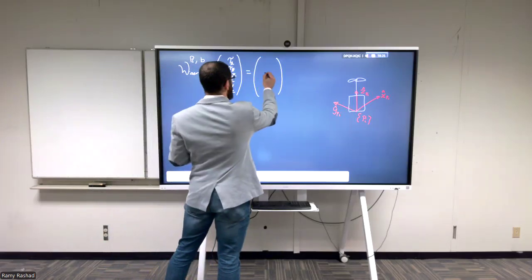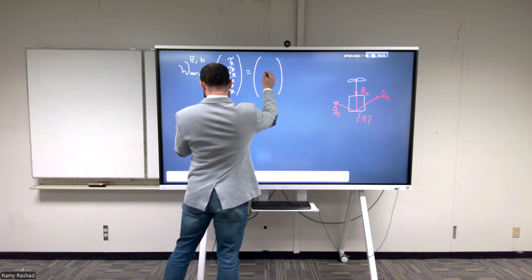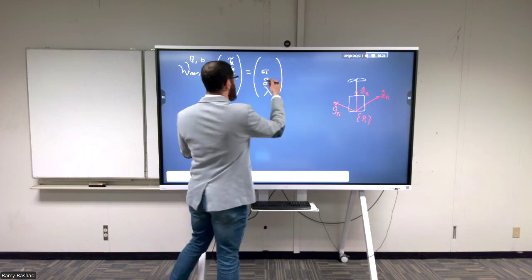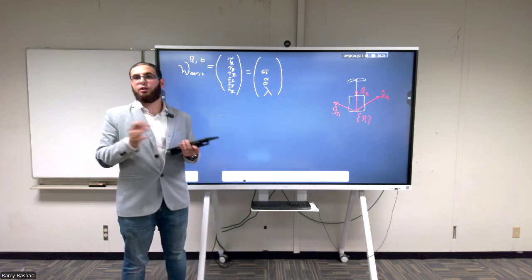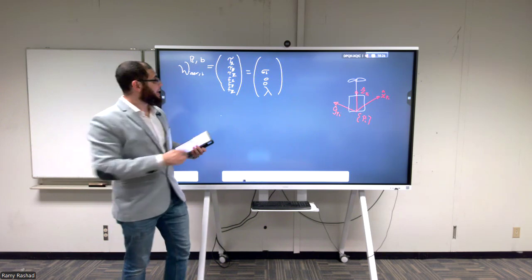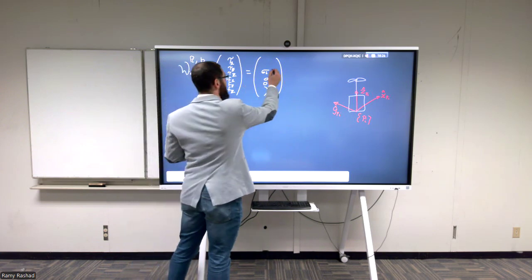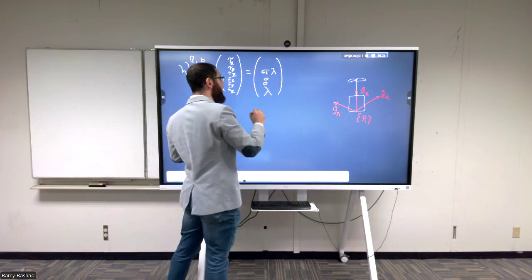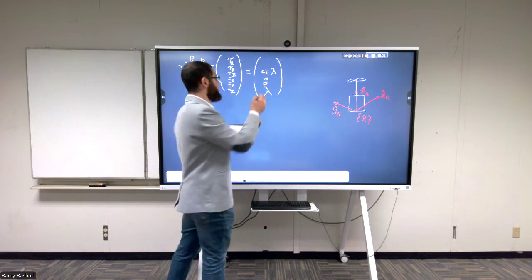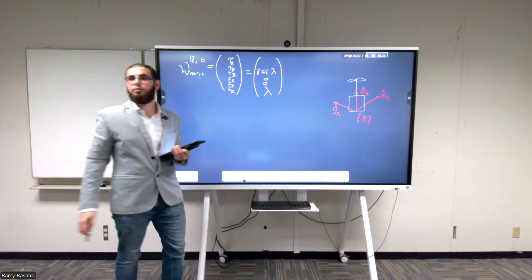So we're going to have here some sort of sigma I multiplied by a torque, but there's a modeling assumption that's very valid, and you can show it in practice, that the drag torque that's produced is usually a constant, or a fraction that we're going to be calling gamma, multiplied by the thrust itself.